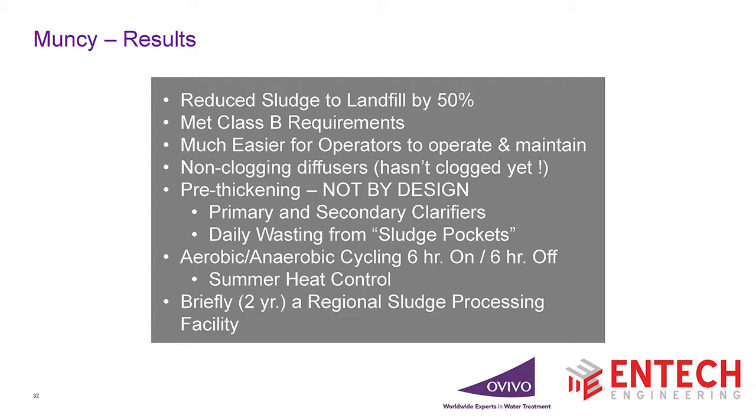So in results, when we went back and measured, we reduced the amount of sludge to the landfill, wet biosolids, by 50%. And that was a real number. That was off the scales at the landfill. We were meeting Class B. It was much easier for the operators to operate and maintain. And those diffusers, 13 years they were in operation, and they never clogged with a manual bar screen. This plant has since been decommissioned. It became part of a regional upgrade in the area.